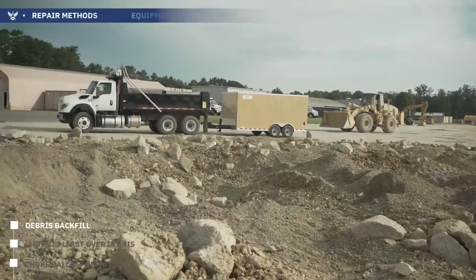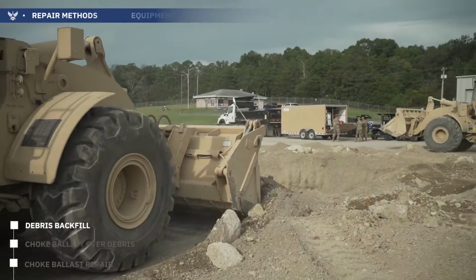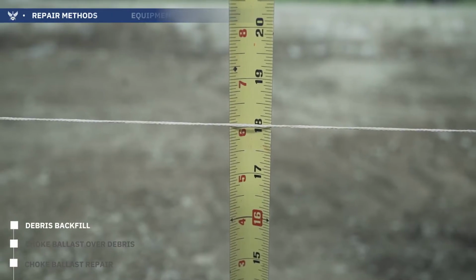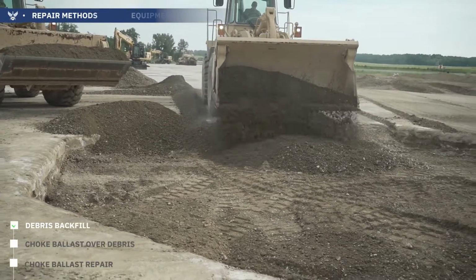Debris backfill crater. Used when subsurface debris is plentiful and suitable for filling the crater. Fill the crater with debris up to 18 inches below the surface. Fill the remaining portion of the crater with crushed stone.